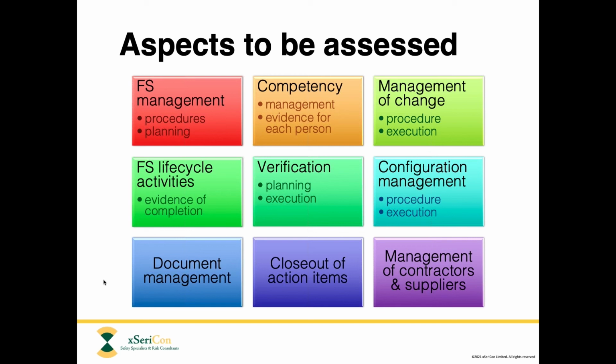So it's really about making sure that the documentation is of good quality and it's being properly looked after. Number 8 is about action items. So any items that require follow-up from, for example, the HAZOP study, the SIL study, previous functional safety assessments, verification, or any other task that can generate action items, we would like to see evidence that you're closing those out.